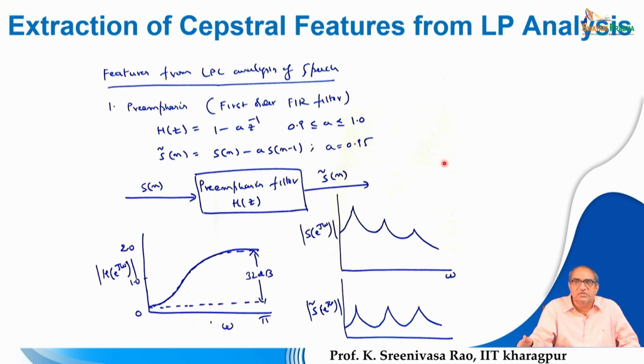The poles and zeros outside the unit circle lead to a non-minimum phase, where the phase of the system keeps on increasing and there is no control over it. Whereas the poles and zeros within the unit circle offer a minimum phase system. If the system contains both, it is known as non-minimum phase or mixed phase, and that is not desirable.